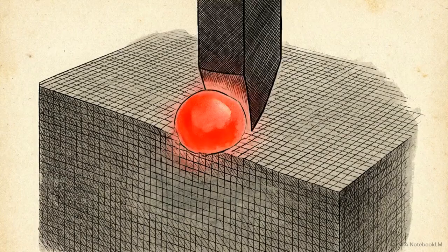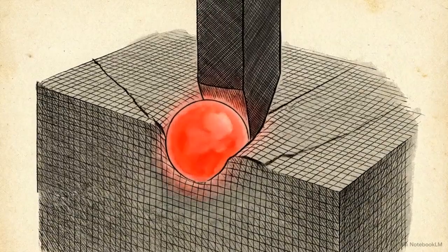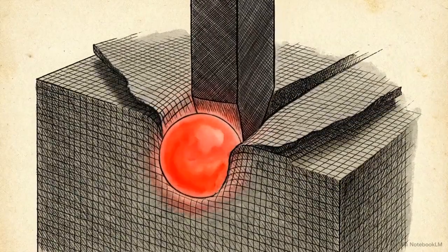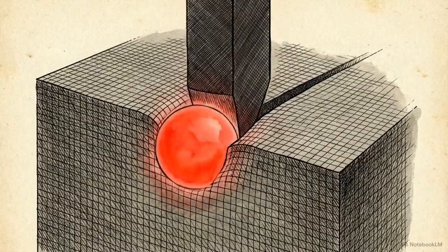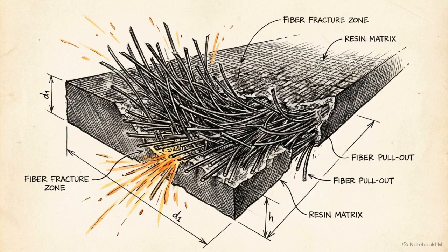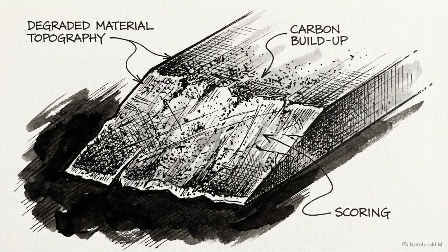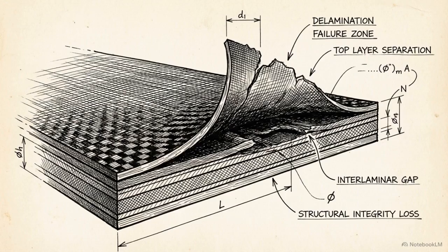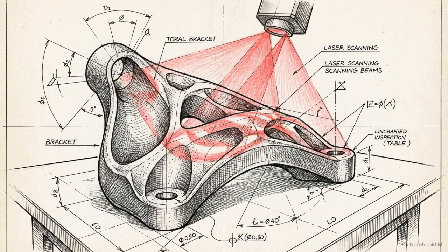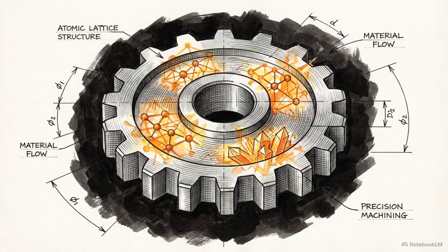In this close-up video, we see titanium's exceptionally poor thermal conductivity traps the extreme heat precisely at the edge. Then there are abrasive composites, like carbon fiber reinforced polymers, or CFRP. The carbon fibers act like sandpaper against the tool, requiring highly specific clearance angles to prevent matrix smearing and the separation of layers, known as delamination. Surface finish optimization is never a universal formula. It is a highly bespoke, dynamic negotiation with the atomic reality of the material being cut.